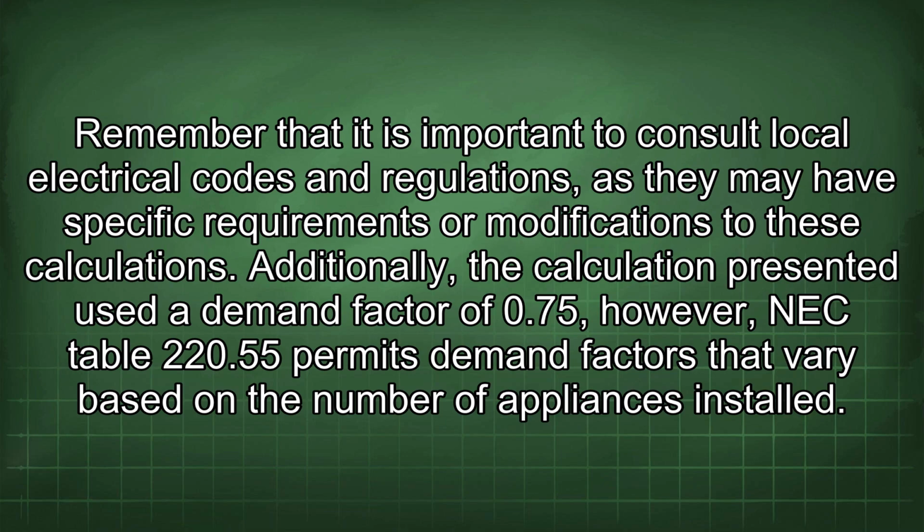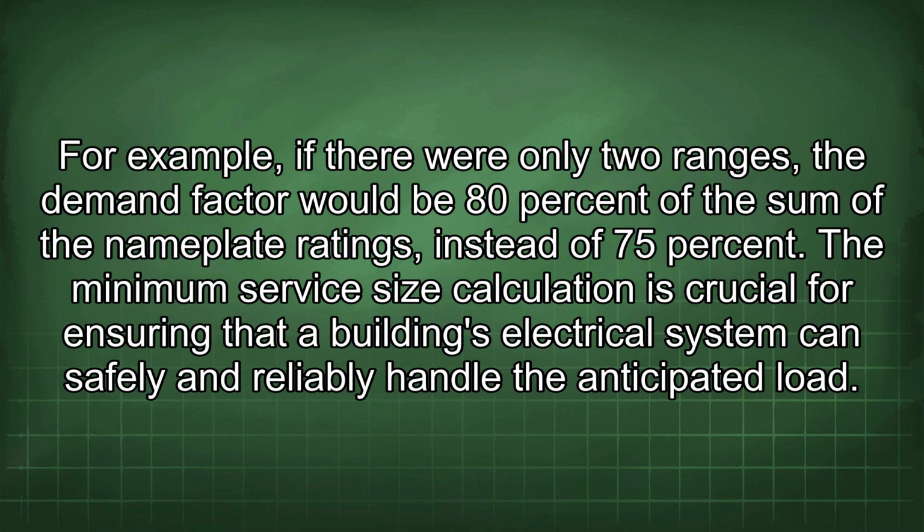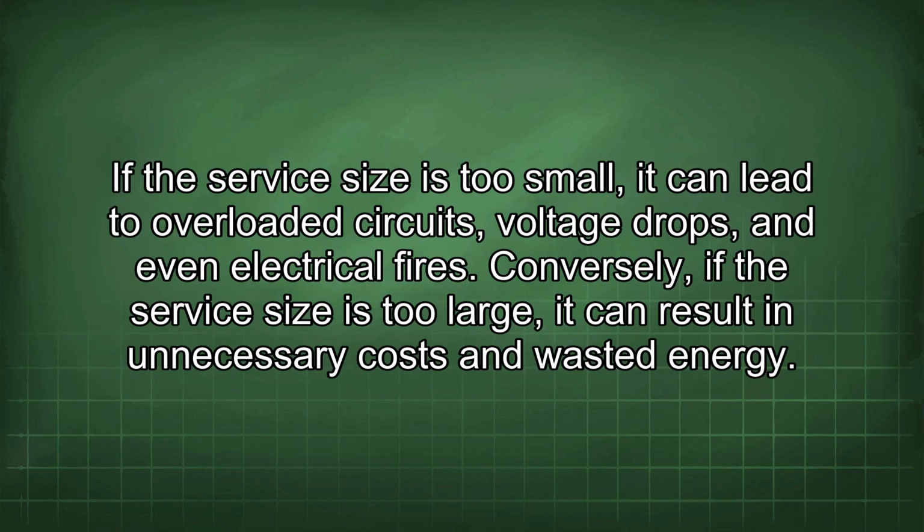However, NEC Table 220.55 permits demand factors that vary based on the number of appliances installed. For example, if there were only 2 ranges, the demand factor would be 80% of the sum of the nameplate ratings instead of 75%. The minimum service size calculation is crucial for ensuring that a building's electrical system can safely and reliably handle the anticipated load. If the service size is too small, it can lead to overloaded circuits, voltage drops, and even electrical fires. Conversely, if the service size is too large, it can result in unnecessary costs and wasted energy.